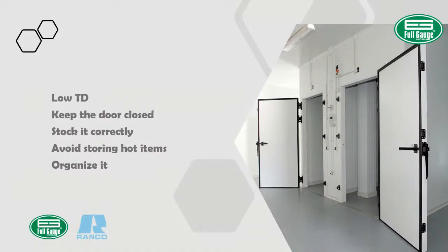Another nice tip for reducing frost buildup is to avoid storing hot items. For instance, in restaurants, when you have a hot pan coming out of the kitchen, especially on freezer applications in low temp walk-in boxes, ideally, you would take that hot pan and leave it in a refrigerated space, let it cool down before entering the frozen space, your low temp device. So that's another good alternative to reduce ice buildup.